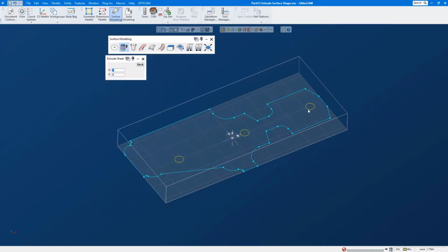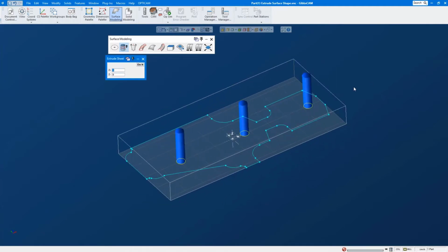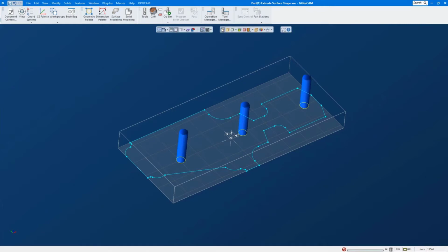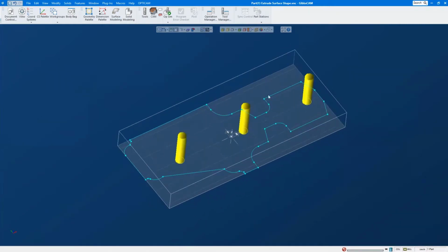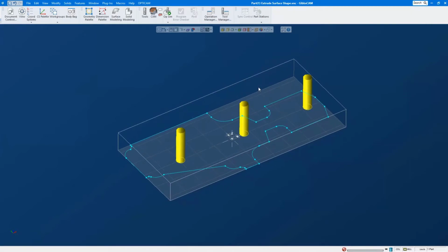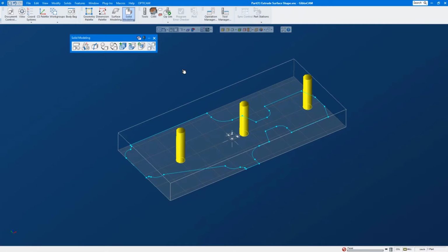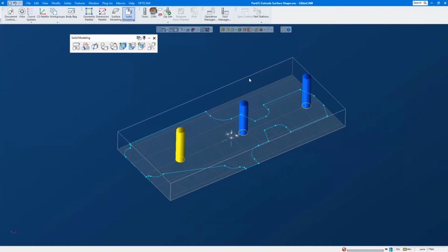The other thing it does is you can do multiple shapes. So even if you had 10 or 12 or 15 pieces of geometry, it will also extrude those, which is pretty cool. Now, keep in mind that these are connected. So they become, again, like a multi-lump body. And if you want to separate them, you need to use the solids, of course, here, the solids to separate them into individual pieces. Okay, so pretty simple functionality, but it's pretty cool.